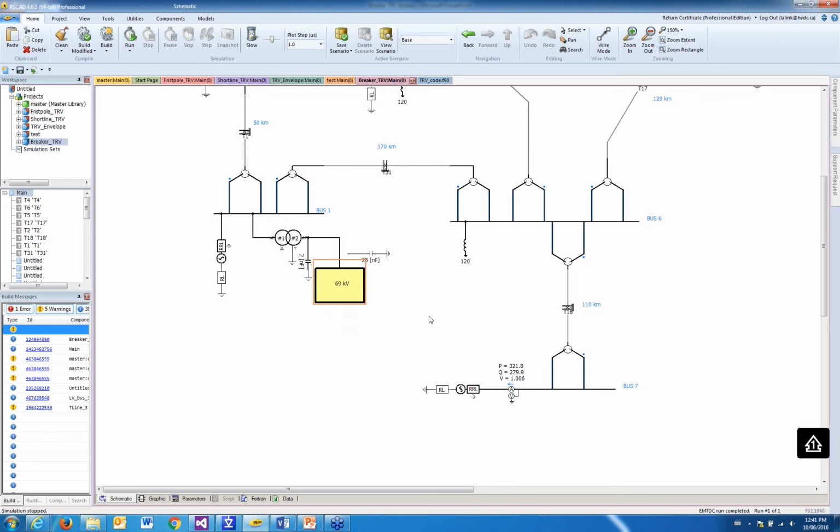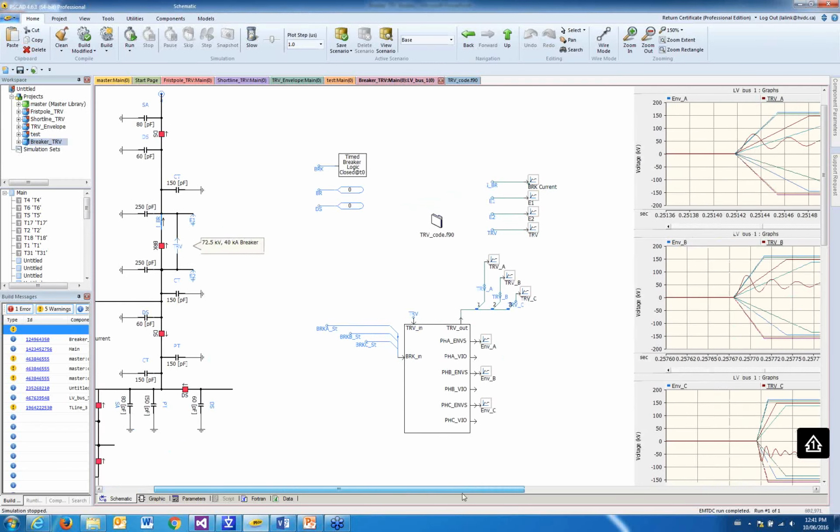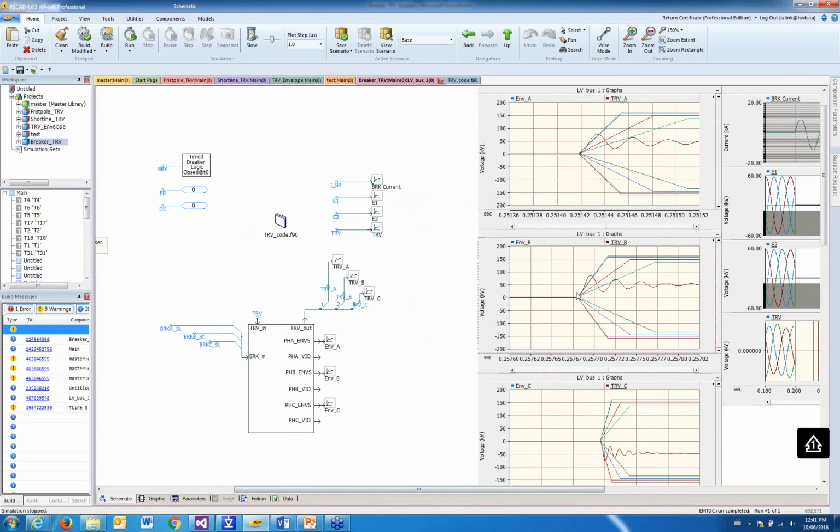For the mitigation, there are several options in this case. Some are really costly. One thing is you upgrade your breaker. Then you have a much expanded set of envelopes, something like this. So you can see whether upgrading works or not, and you can take a higher breaking capacity breaker, then your fault current percentage will be lower.